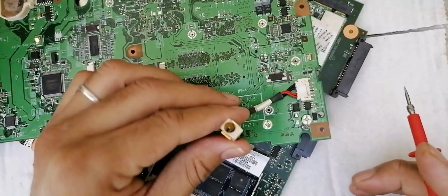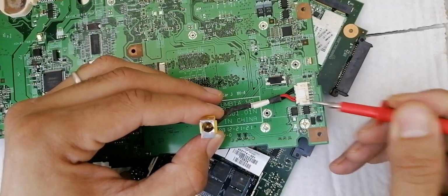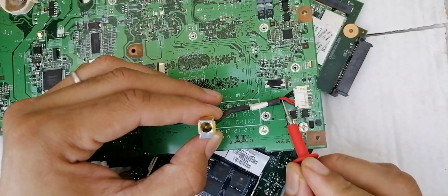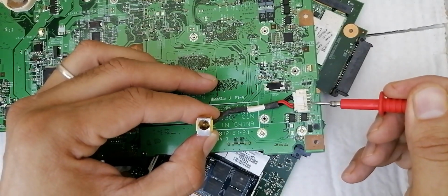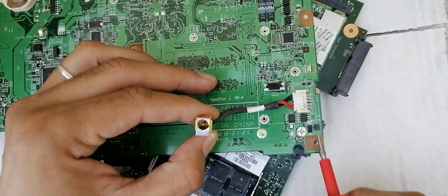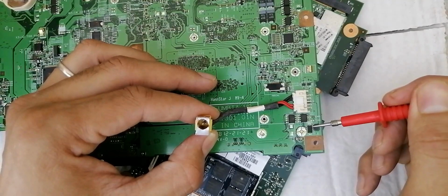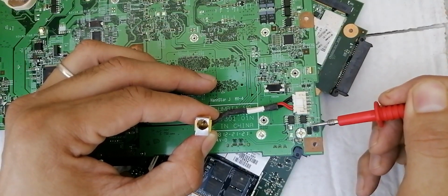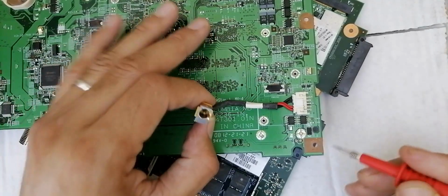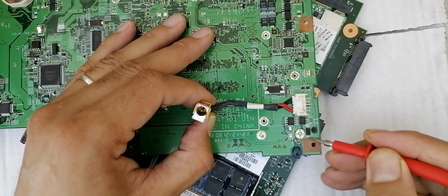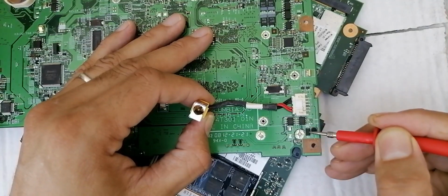Okay. For this motherboard, for example, this is a power jack with cable. You should find here a 19 volt in the red terminal. Do you see a red terminal? So the fourth step is to check the red terminals here. You should get 19 volt, and also in these switches you should get 19 volt, and also in the cathode of this diode. Okay, this is basically a protection diode. So the anode of the diode is connected to the ground and the cathode connected to main volt. This is a protection diode.